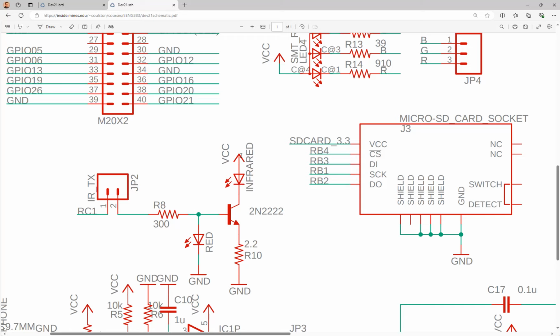So here's VCC, it's a power supply. If you turn this on, the channel here is on, so it's going to flow current through it. It's a gate, yeah, it's a switch. And it is able to amplify the base current through this collector current by a certain level. It's called beta, usually it's 100 or something, so times the current, but that's not important though for here. We just need to know that you send the pulses, you give a 1 here, and it's going to turn it on. You give a 0, it turns it off. So 1 will turn on the LED. 0 will turn off the LED.